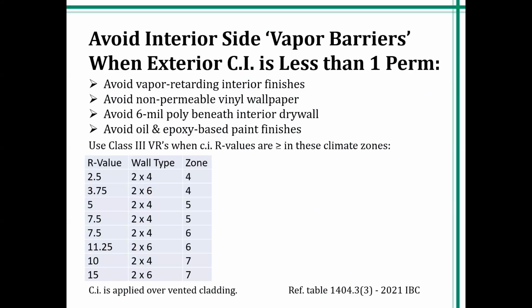Again, vinyl covered wallpaper that's not perforated, epoxy, oil-based paints. These all constitute, quote, vapor barrier. Now, there are always exceptions to this. I've had a number of projects that I've assisted with where they have to have a spray down room where they're cleaning things, or maybe it's a laboratory. And they said, yes, we do in fact have epoxy covered paint. Well, I would challenge that if that's effectively, for all intents, a clean room.